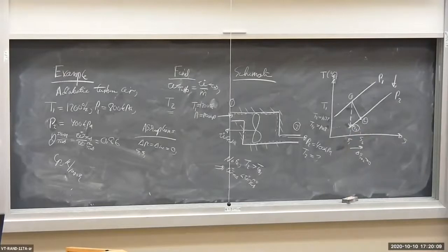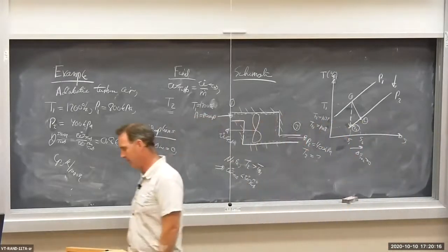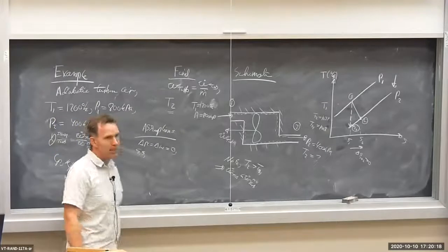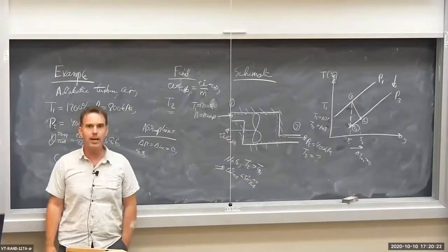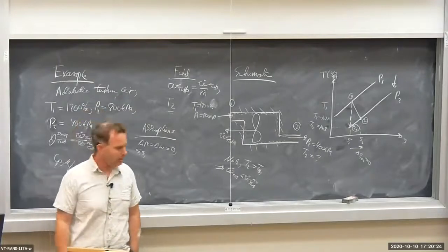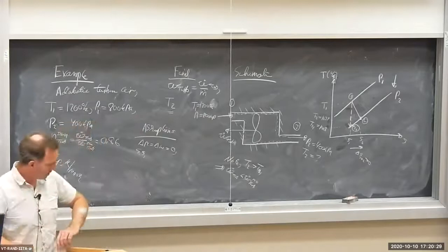It produces no power. The outlet temperature, T2, would be equal to the inlet temperature, T1. Not much of a turbine, but it is definitely an illustration of an extreme example. An extreme and a generality: real turbines will have a hotter exhaust temperature than an isentropic turbine.